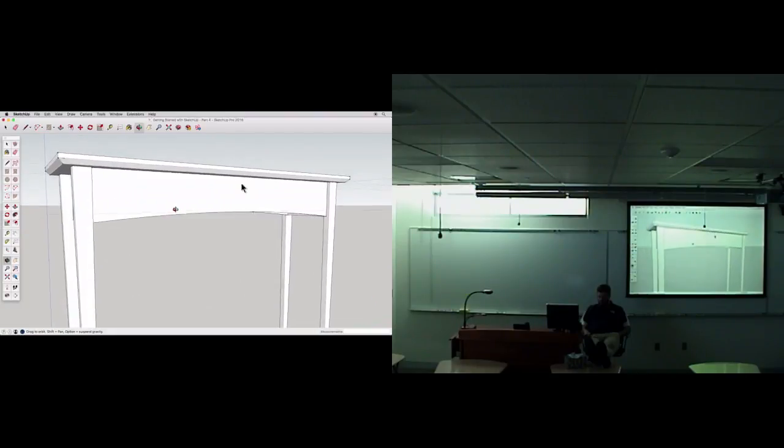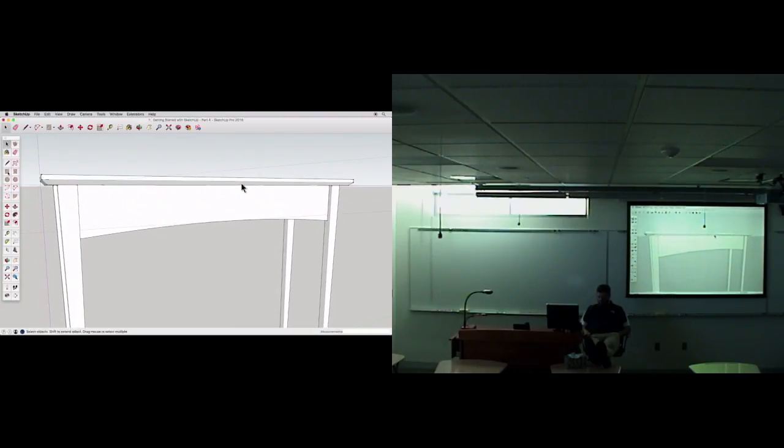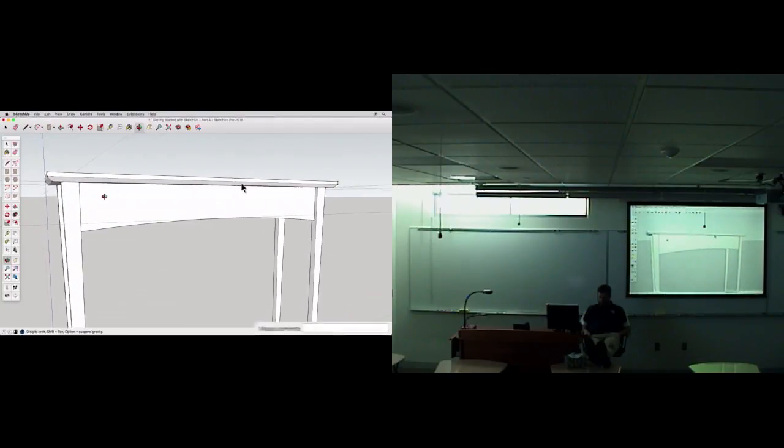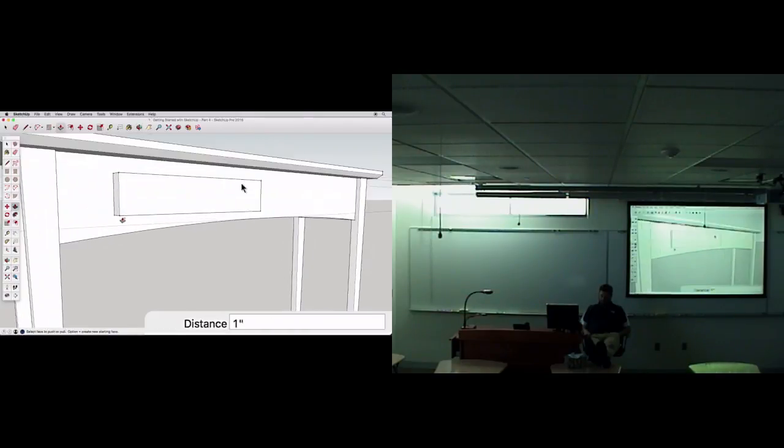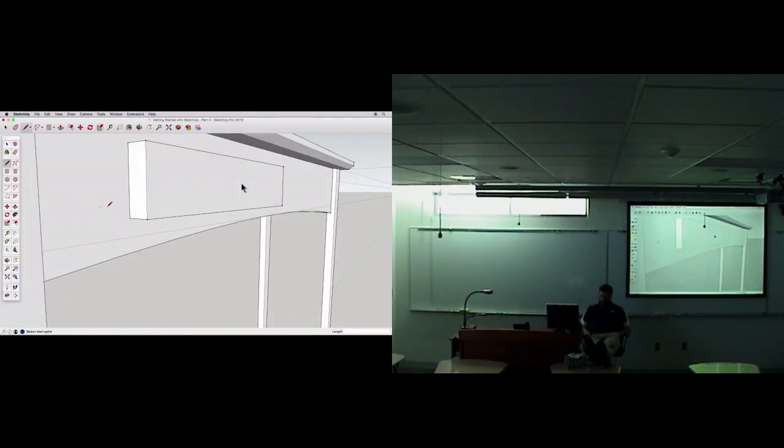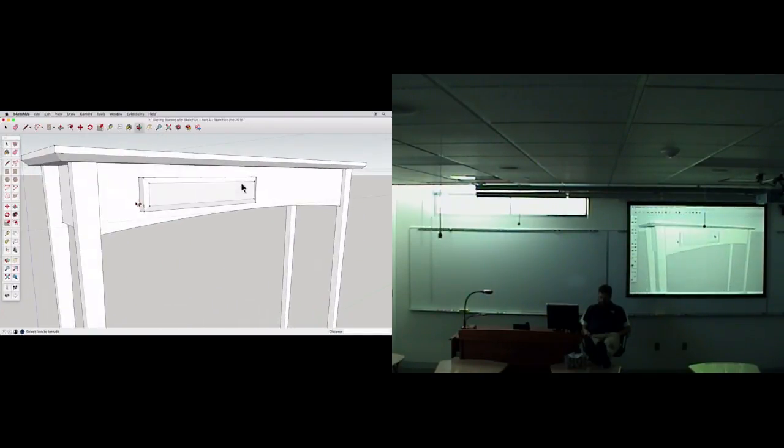We won't create all the internal elements or drawers that a real table will have, but let's finish this example by creating the drawer fronts so our table looks complete. Draw a rectangle on the table front that is 3 inches by 15 inches wide, and pull it out an inch. Zoom in and create a chamfer as we did with the tabletop. Draw an angle, then select the front face as our Follow Me surface. Then choose the Follow Me tool and click on the angle to complete the Follow Me chamfer.